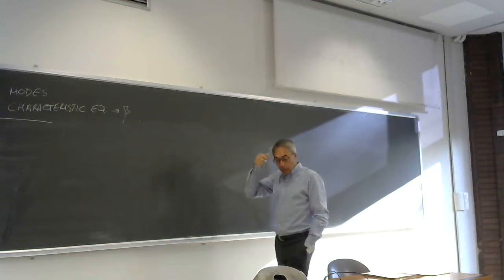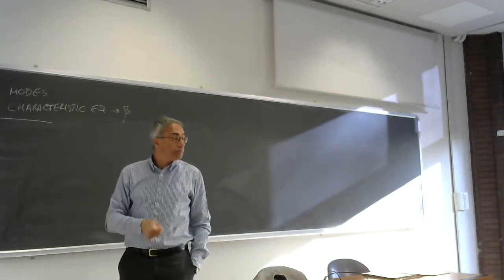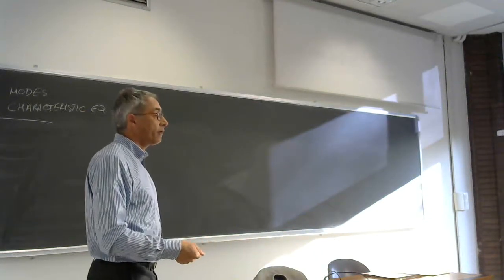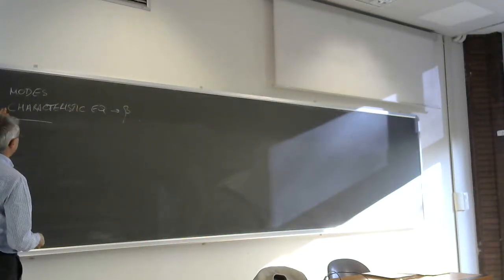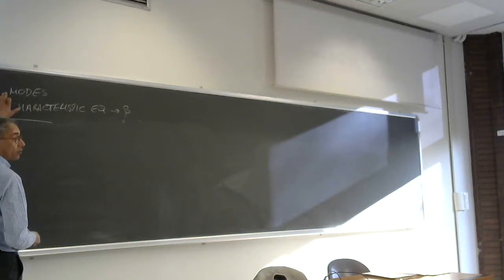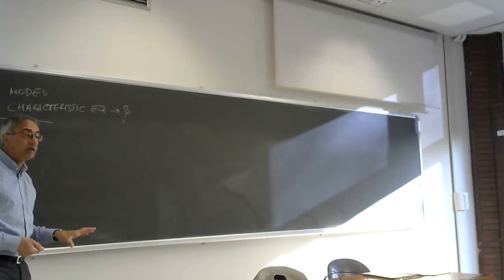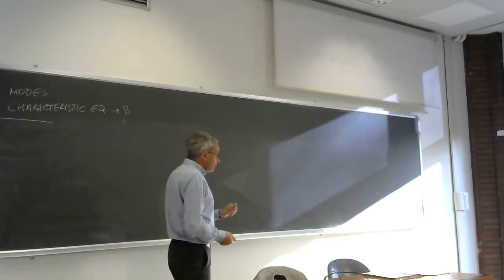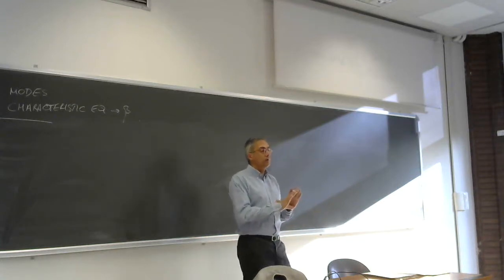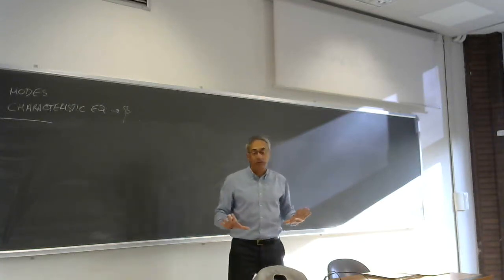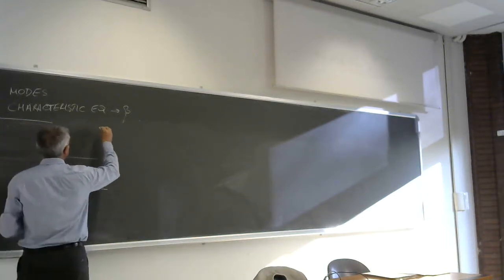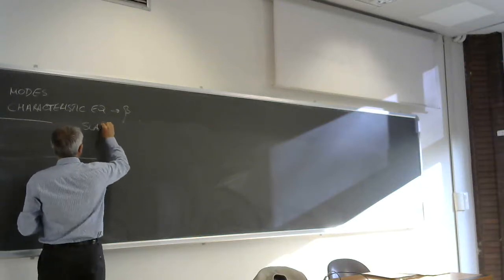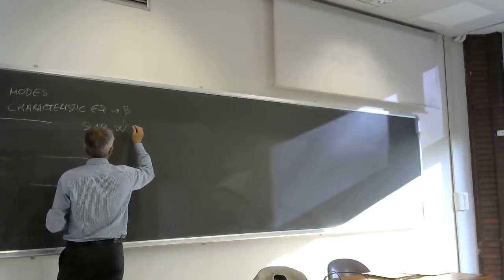So this morning we use this approach, wave equation, try to solve the wave equation analytically, and so calculate once again the characteristic equation and the modes and the shape of the modes and everything else, all the characteristics of the waveguide. It's not easy to do, so we choose the simpler structure as possible. That is a slab waveguide.